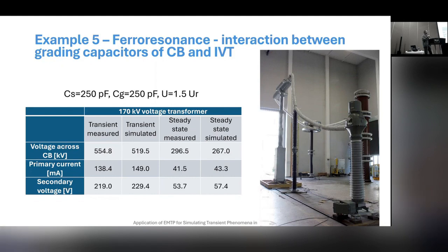let's say, to see if the test will be carried out, in which type of test do you expect ferro resonance to occur? Because when that happens, you may even have some failure of the measuring equipment and so on. So it can be dangerous. It's easier to check with EMTP what you can expect during the test, and then you can prepare the test. It is safer to do this procedure that way.